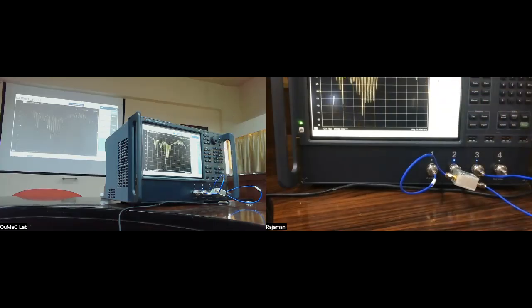Not loss. I mean, that's the reflection. The reflection is worse in this. It's just something in the design. Ideally speaking, it should be the same, but the output ports and the input ports are not exactly the same in terms of the structure of the circuit. Okay. So later on, when we actually study this particular splitter, which is a type called Wilkinson divider, you will see how it's actually constructed inside, like what are the input transmission line and output transmission lines.